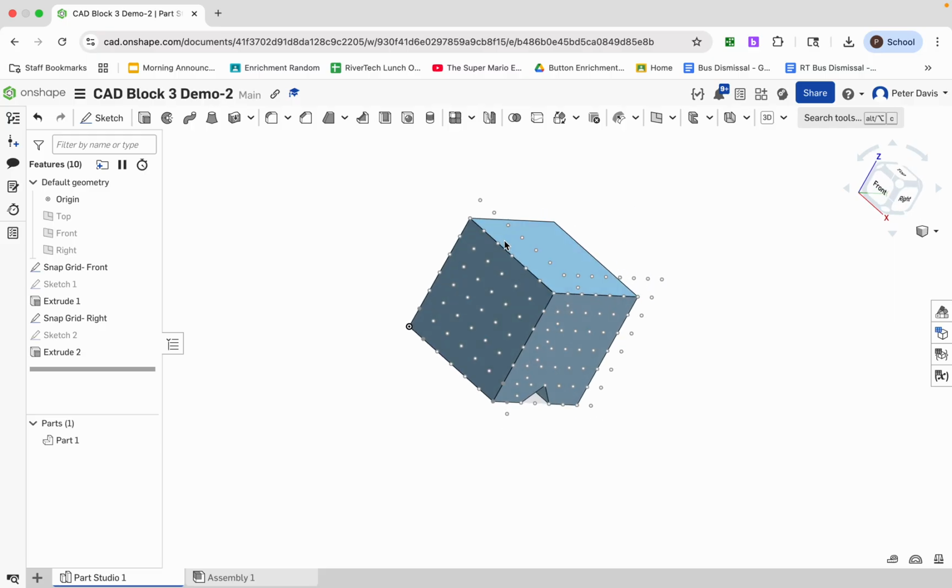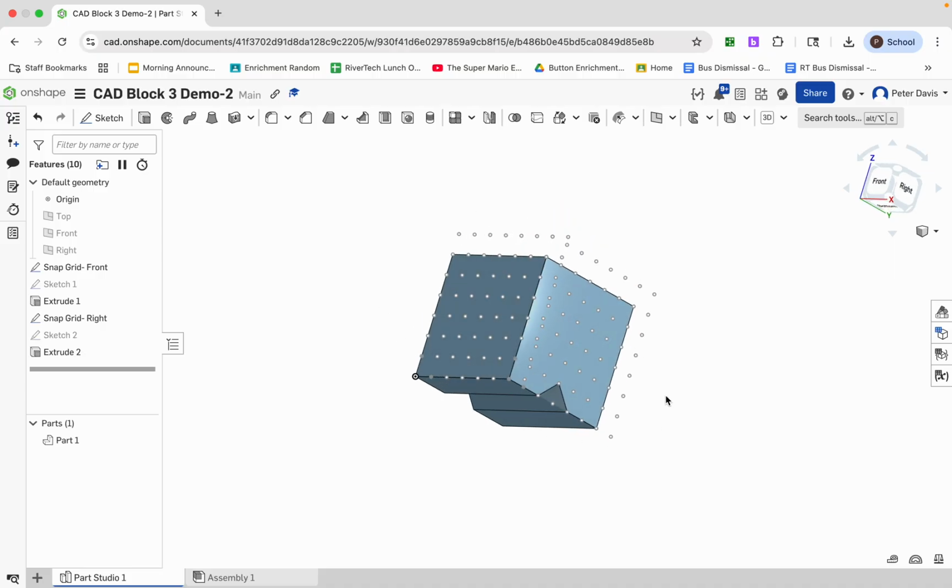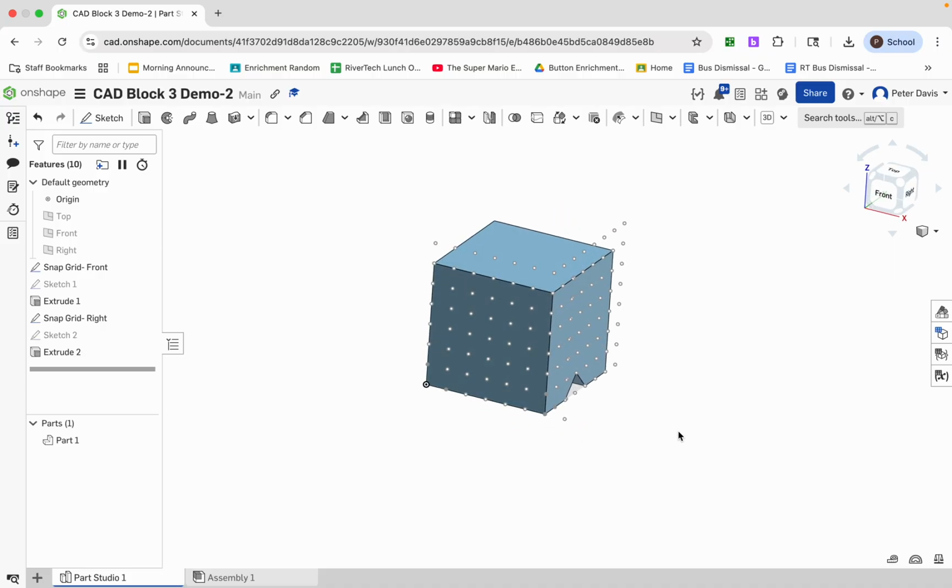That's good. So the last thing I need to do is figure out how to do this notch up in the corner. Okay, the notch up in the corner is unique. It's not at 90 degrees to anything else I've got. So in this case, I need to create a reference plane that allows me to cut at that 45-degree offset angle or compound angle. So the easiest way to do that is for me to come up here and use what's called the plane tool. I can create a reference plane.